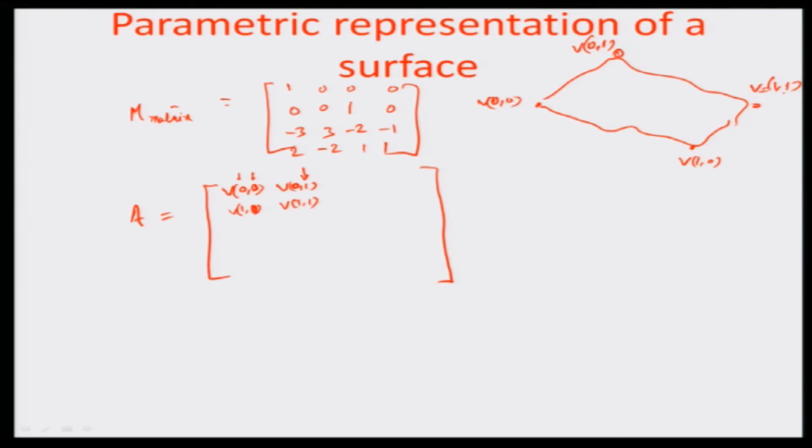So these are the four corners. Obviously these points have been given in the arguments of the question, and then there are the various slopes with respect to the t direction. So you have the slope at the point 00, slope at the point 01, slope at the point 10, and slope at the point 11. That is how the A matrix has been formulated. Okay. And the slope with respect to s, now this was with respect to t, meaning thereby d by dt of that particular function. Now this is the d by ds of that particular function. Obviously there are two parameters, so there has to be a derivative in t and a derivative in s. Both the parameters should have derivatives or slopes along their own directions.